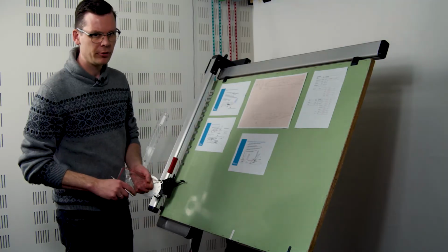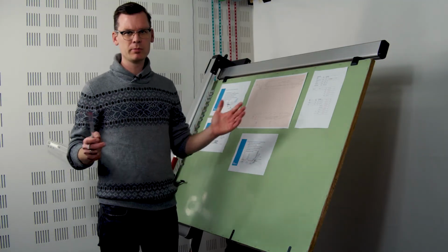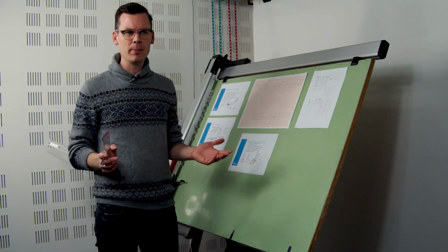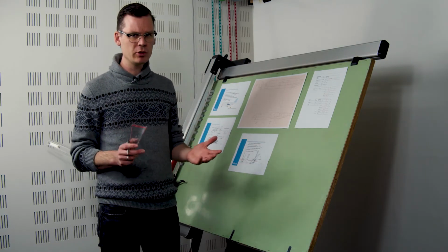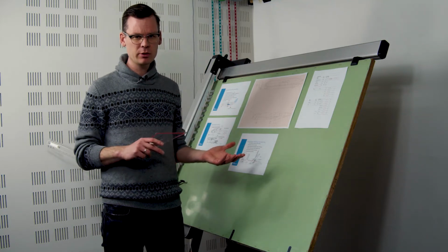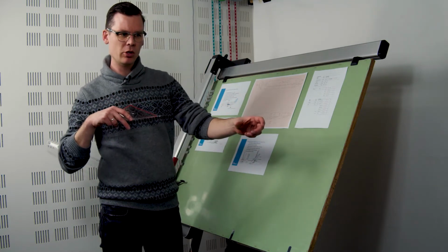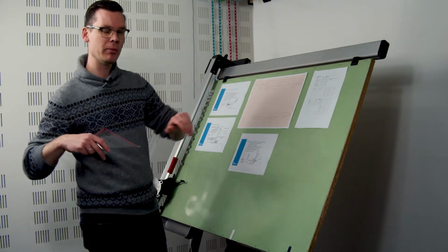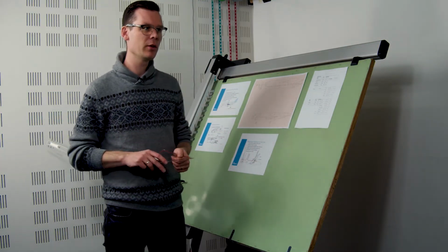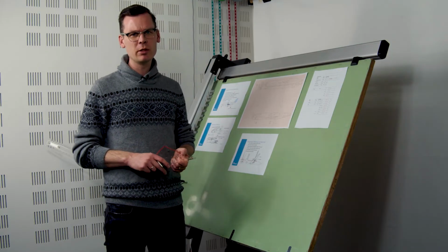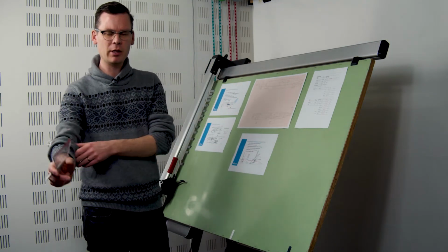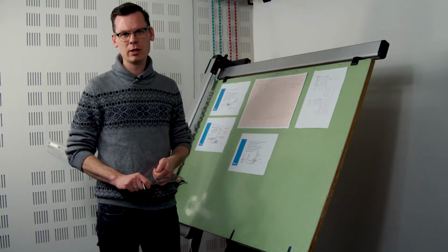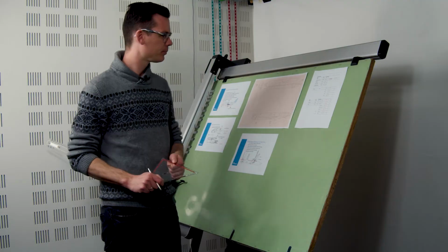Okay, so the first thing we now need to do is determine where this main landing gear wheel needs to be in the lateral position. And we're going to look at two constraints. One is the lateral tip over constraint, so the fact that it doesn't tip over the nose wheel and one main wheel when the airplane is, for example, making a turn. That's one constraint. And the other constraint is the clearance constraint, making sure that the wheel is sufficiently far outboard such that the wing tip is not touching the ground during a banked maneuver.